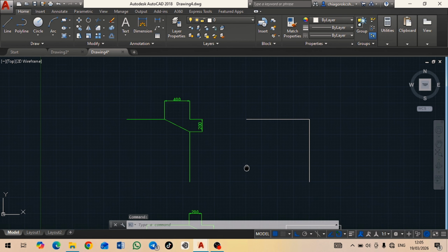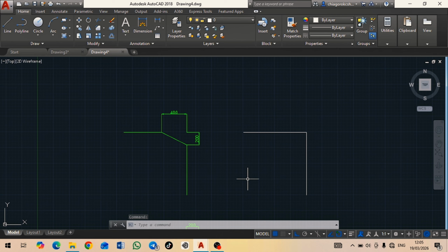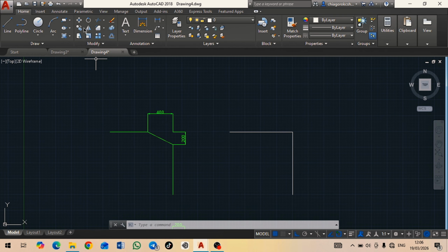Make use of chamfer this time around. We can chamfer by using two different methods. We can specify the horizontal and vertical distance of the chamfer, or we can specify one of the distances and the angle. But let's see the difference in examples. In this first example, we are going to activate the chamfer this time around, not fillet. Click on chamfer.